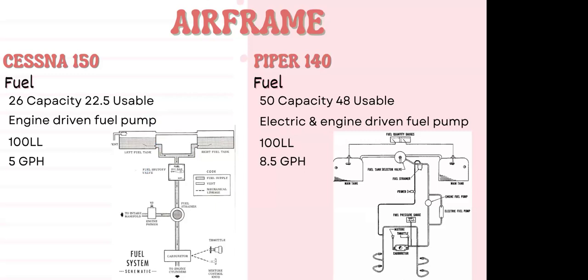It will tend to equilibrate during flight, and this is also because, although it's cropped out here, the left tank is the only tank with the vent, so it will tend to want to drain from that left tank over the right tank. So it will tend to want to come back to an equilibrium in flight. The other thing you can do is always do a steep turn to the side where it has less fuel if you wanted to try and even out those tanks, but it should be all right.